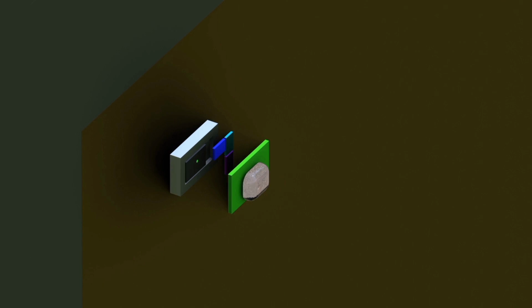This array of photodetectors forms the image sensor chip located at the focal plane of the lens assembly. Around the pixel array, there are analog and digital circuits used to process signals and assemble the final digital image. For example, a 16-megapixel camera contains 16 million individual pixels, each extremely small, but working together to create a detailed image.